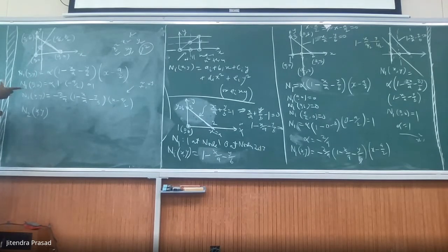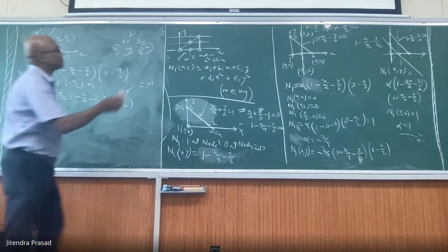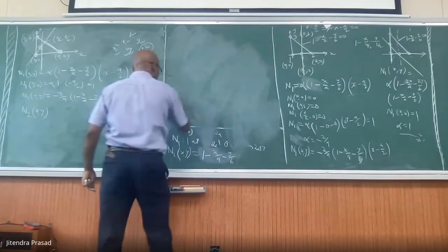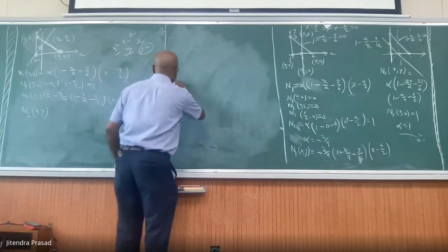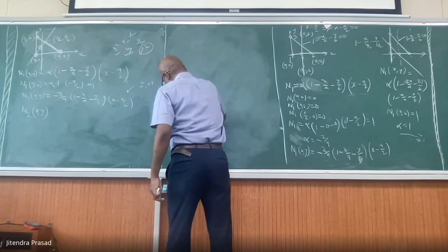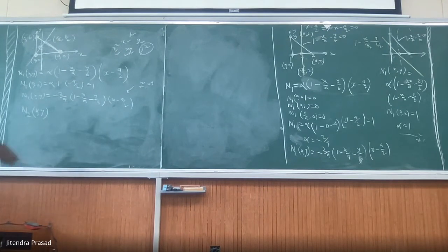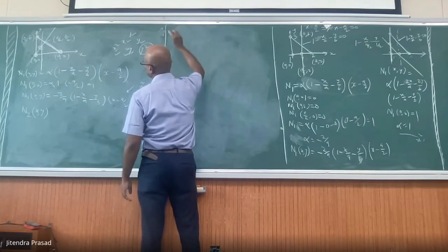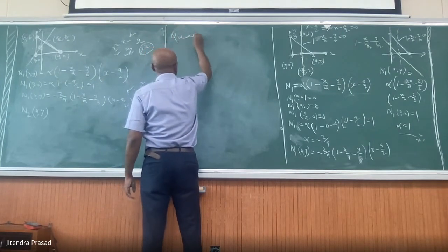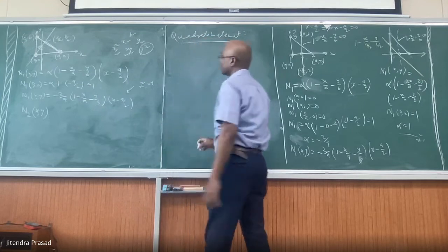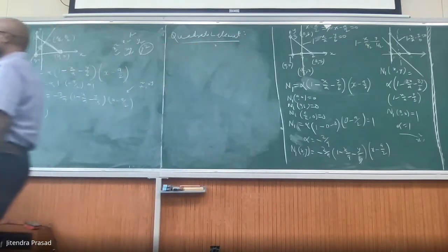Yeah, we will see more, and this will help when we go to what is called the isoparametric element, and then we will revisit these things again. But anyway, we discuss it because it gives some insight. In some way we look at the elements and try to guess what the shape function will be. Now, the quadratic element, where it will work, will be one example. So the quadratic element, actually this is a rectangular element.